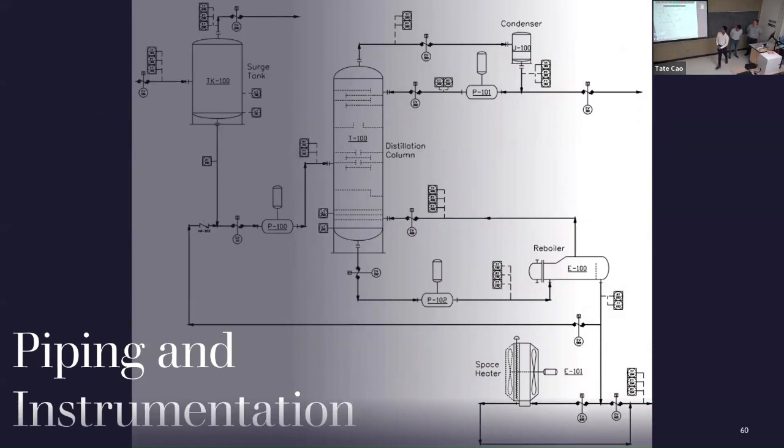Okay, so since this system is operating on the moon, a lot of thought and consideration had to be put into automating it. So we have a lot of sensors, control valves, and pumps, all feeding off of each other and communicating with each other to optimize the processing of the water. As Hariel said, once the liquid is put into the distillation column, it's really important to have a temperature gradient across this, which is what's used for the separation, boiling off the volatiles and leaving water as the product.